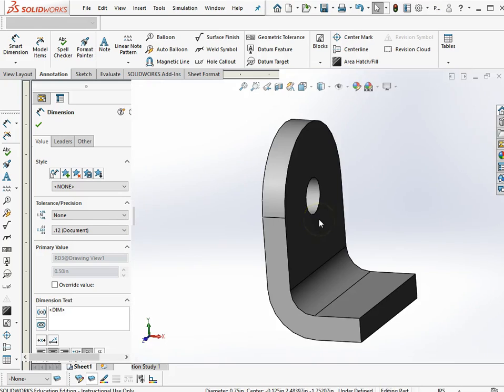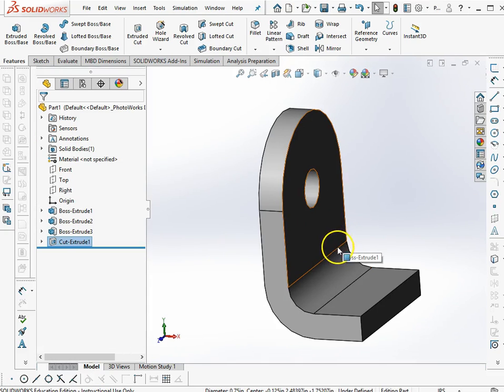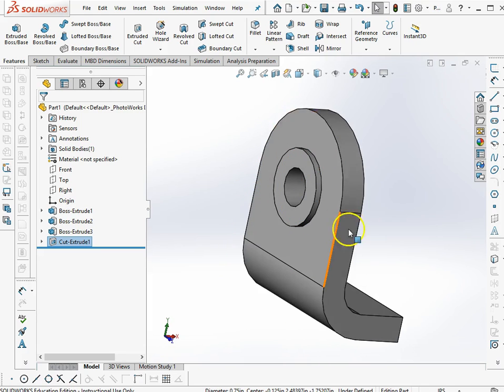Now, the easiest way, I showed you how to do a sketch fillet earlier. That was what we used for here, though that's a little pushing it to call that a fillet, but we did anyway. But this one's a little harder to do that way because it goes around a circle. It's hard to think of how to draw a fillet that way. But fillets are so common that SolidWorks has given you a special tool, and that's called a fillet.